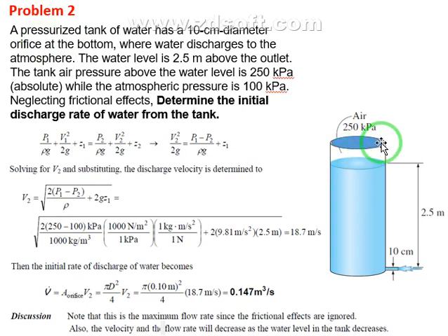Because we have a closed tank. So this cover here will separate the water inside the tank from the atmosphere, so we can't consider this pressure as atmospheric pressure. So now we can't assume that P1 is gonna equal P2 atmospheric pressure. No, at all, we can't do that.